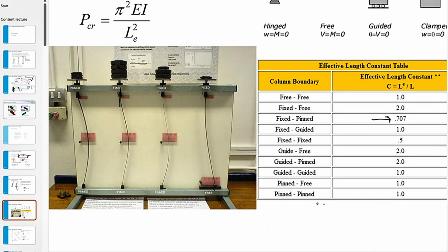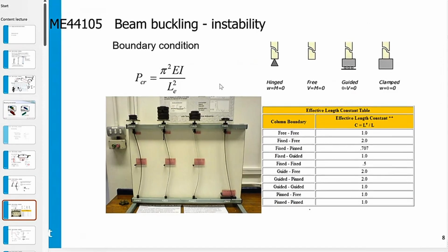By default, standards assume the standard situation, so with a buckling length of 1 times the beam. Take that into account, because that means that you can use this effect for modification of the real buckling length in your model.